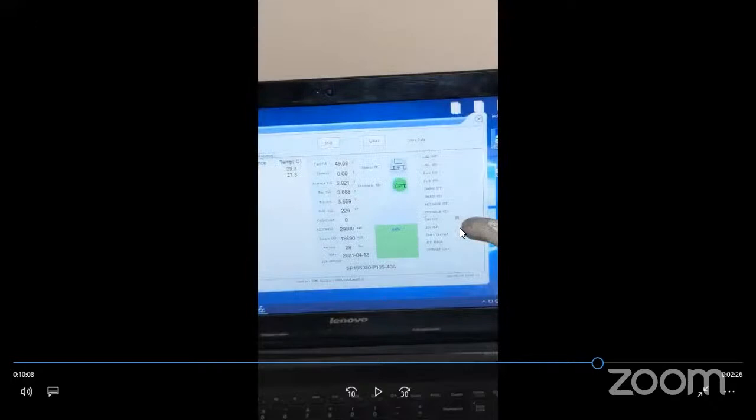This is the red symbol which you saw on the charge OCP, right? That indicates it's a warning symbol. The BMS has cut off due to a particular reason. So this is your complete warning window where you will see this signal, which indicates which particular parameter has attained the protection level.